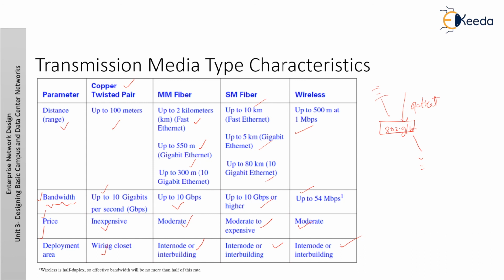When deploying devices in an area with high electrical or magnetic interference, for example in an industrial environment, you must pay special attention to media selection. In such an environment, the disturbances might interfere with data transfer and therefore result in an increased number of frame errors. Electrical grounding can isolate some external disturbance, but additional wiring increases cost. Fiber optic installation is the only reasonable solution for such networks.